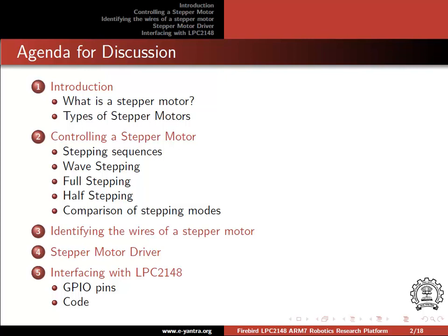Let's see the agenda for discussion in this tutorial. First, we will have an introduction where we will discuss what is a stepper motor and its types. Then we will move on to learn how to control a stepper motor in different stepping sequences like wave, full, and half stepping modes, followed by a comparison of the three stepping modes. Then we will have a short demonstration of how to identify the wires of a usually unlabeled stepper motor. This will be followed by a discussion of the circuitry required to drive a stepper motor, and then finally we will jump on to actually programming the robot to control the stepper motor.